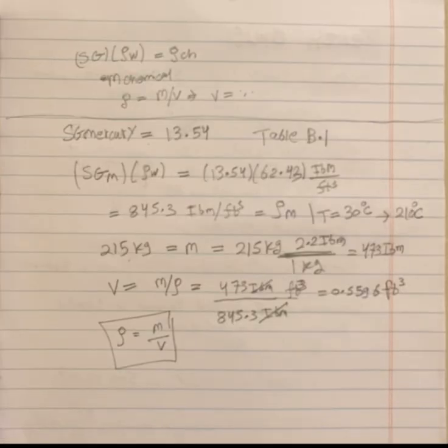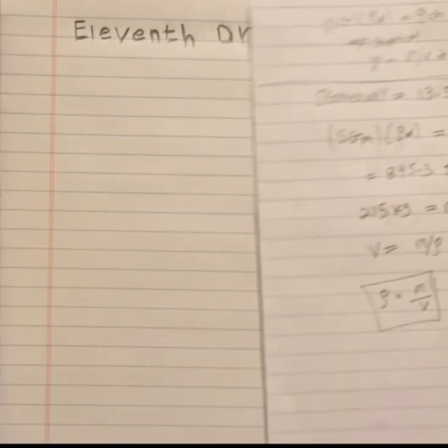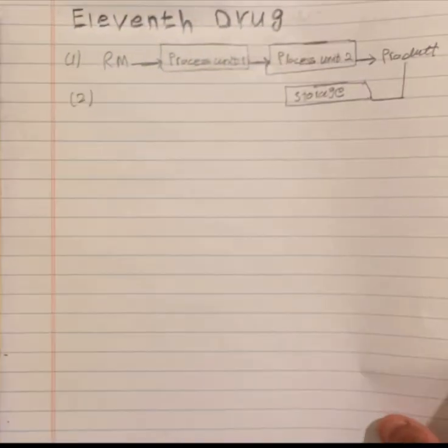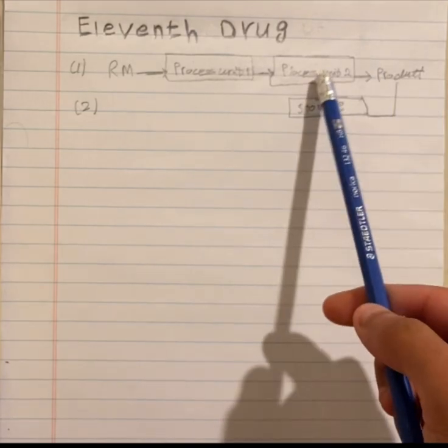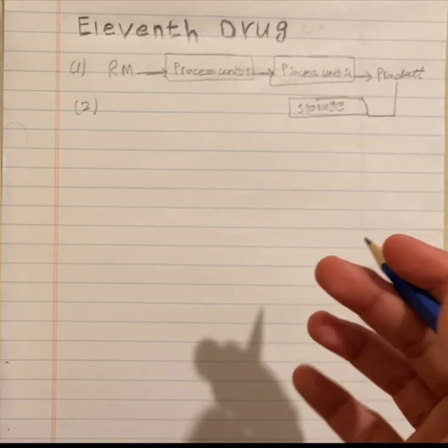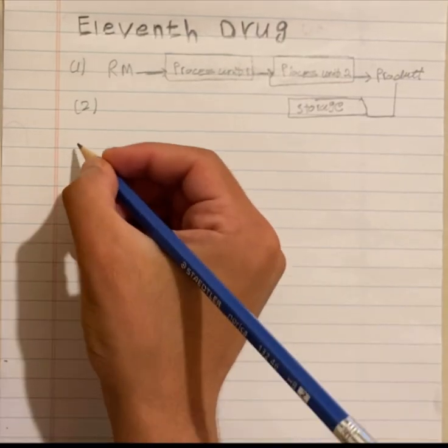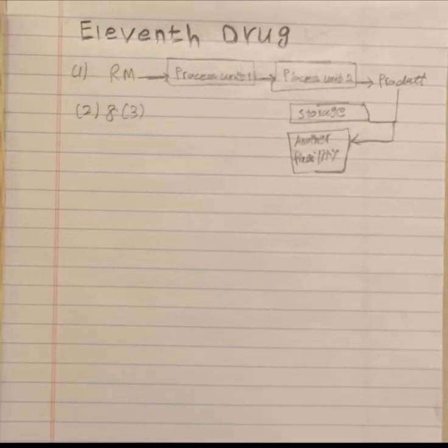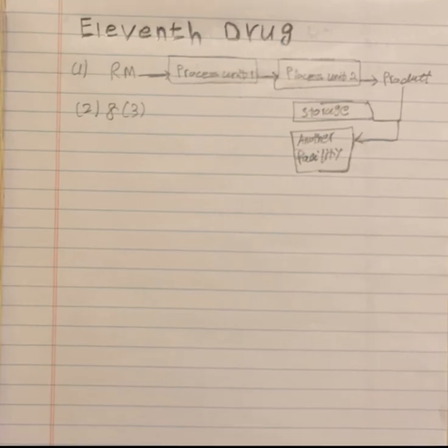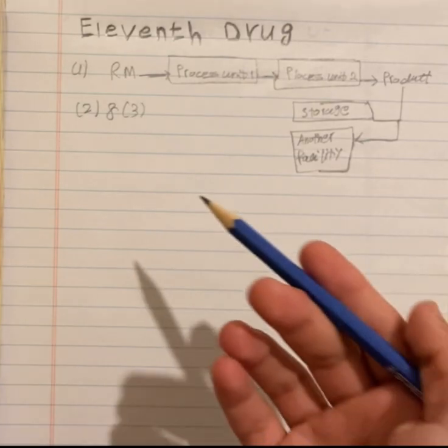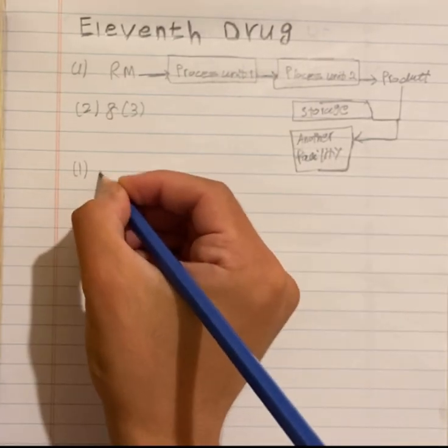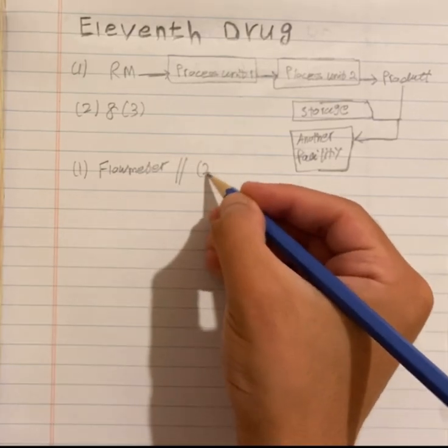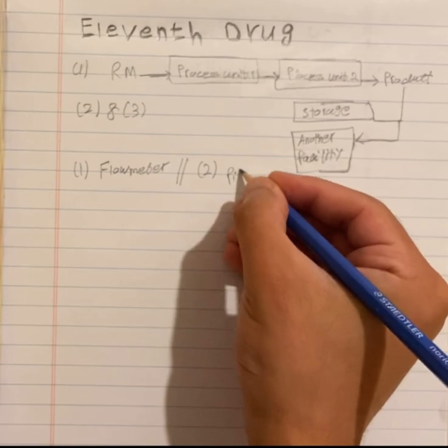I really did say it a lot, but only because it's very important, and because in industrial processes we have always chemicals moving, either entering from a process unit to a process unit, like this case, number 1, or number 2, either leaving as a product, maybe stored in the same facility or an industry, or number 3, maybe leaving to another company or another facility. In all cases, we would need to know the value, and the way we measure the flow rate is by common 2 methods. One is flow meter, and the other is velocity measuring devices like pitot tube.